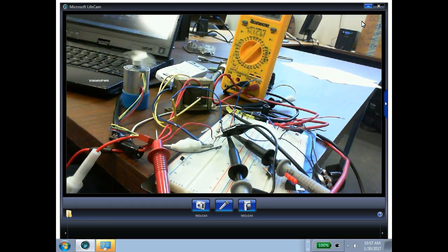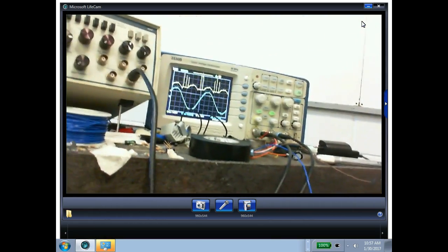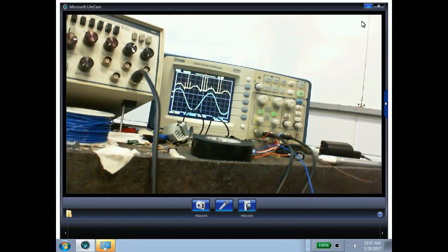So on a half wave, you're going to get that little buzz because the current is being pulsed into it, but it still averages that out. By the way, this is a problem we have with DC motors. So I'm going to come over and take my DC motor out. Oops. I removed one of my power leads. Sorry. I turned a full wave into a half wave.